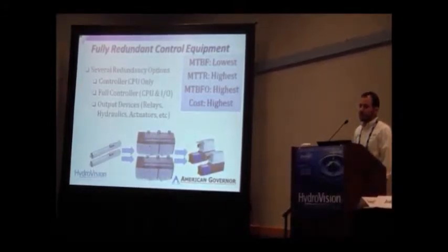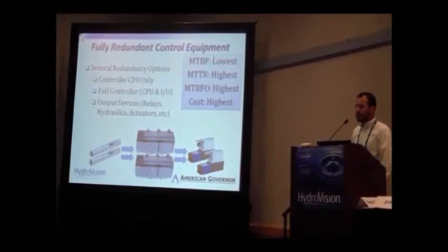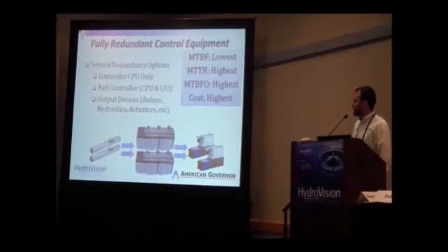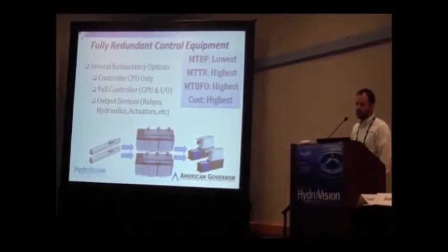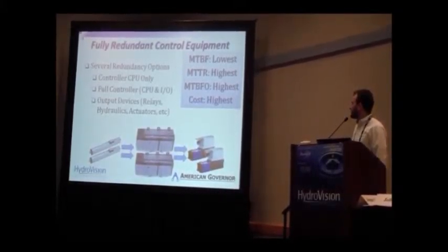Now, step past this is full-blown redundant control. And there's actually several layers here we're going to talk about. The simplest is redundancy of your controller's CPU only. Next level would be a full redundant controller, including CPU and I/O. And then finally, looking at your output device.